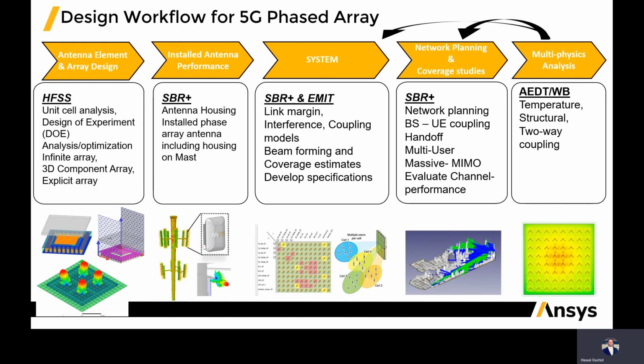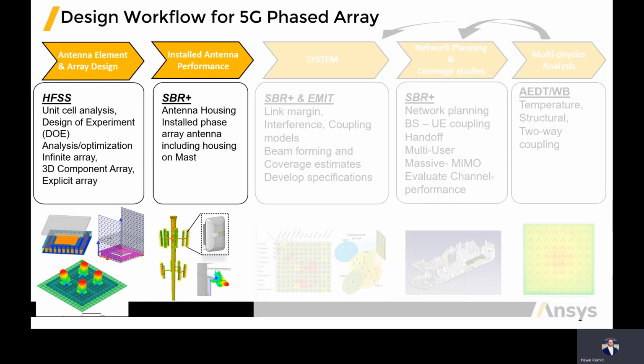And obviously for these radio units, multiphysics becomes an important part of it, because what happens to the radiation pattern if you are increasing temperature? What is happening to your mechanical structures when you're increasing temperature? Do you have deformation? And if you do have deformation, how would that affect your radiation properties? This could all be simulated in an integrated workflow within the Ansys suite. But today I'm going to focus only on these 2 parts, and mainly on the antenna synthesis and analysis.